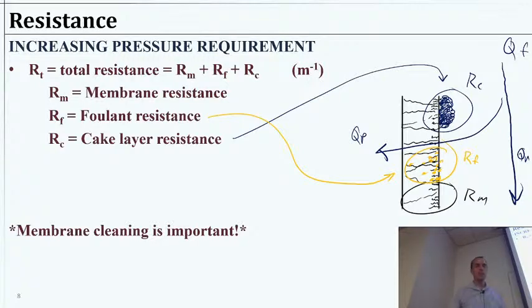All that to say, membrane cleaning is quite important, and if you ever work in the field, you'll see many times people try to restore the flux back to a nominal starting point as if it was a clean membrane. That's kind of the target. Can our cleaning cycle get us back to normal? Can we operate, watch how it drops, the flux or the pressure or whatever, however you want to measure it. Can we bring it back up to kind of a clean status?